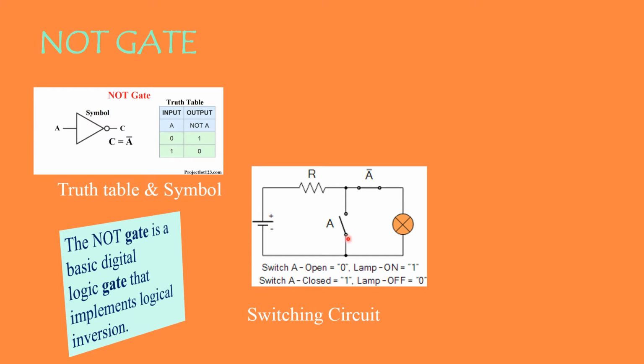So whenever my switch is closed, you'll have a low output because at this point it would be grounded. So you'll have your supply grounded. Whenever the switch is open, this will make a full circuit.